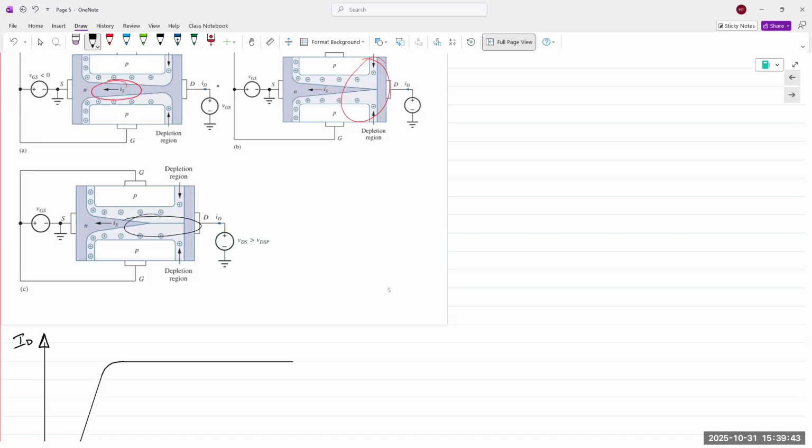So now in the depletion region, again, as the name suggests, it is completely depleted of charge carriers. There are no electrons present in there. So there's an imbalance of charge carrier concentration. There's heavy concentration of electrons in the channel, and then right across in the depletion region, there are no carriers. So there is a depletion, there is a gap in the concentration.